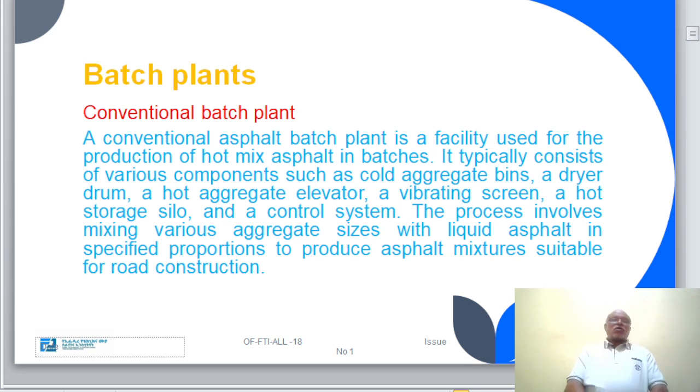The basic disadvantages of conventional batch plants are as follows. High capital costs, relatively high maintenance costs. Overall, higher production costs over drum mix plants. Heat and aggregate materials wasted on overflow material. Capacity being restricted to mix cycle and mixer size.